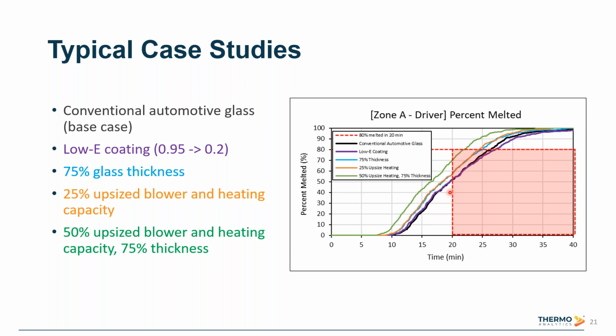A little bit surprisingly, it showed little to no effect in this case. Might even be slightly worse in some cases towards the tail end of the defrost. I think the dashboard's also getting quite hot, so in some cases we're actually receiving radiation heat to the windshield.